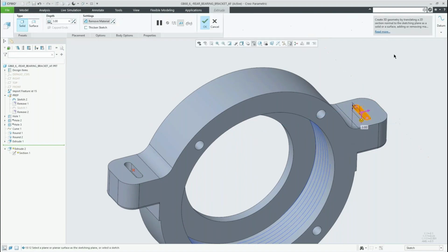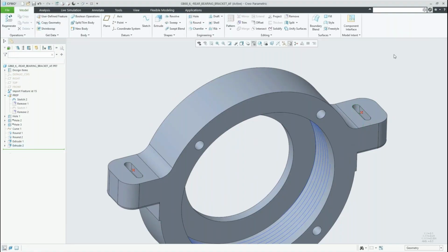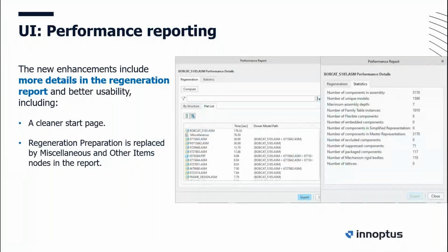And then last thing, I guess it just passed a little bit. You can also right click on the hole feature and you see the presets already. So instead of going first into your hole feature and then choosing a preset, right click on the hole feature and it goes directly into the presets.